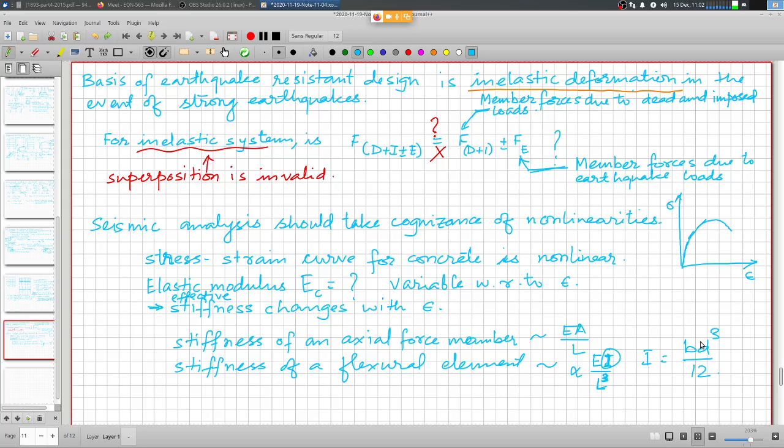And that is why you have so much reservations about the concept of flat slab, wherein the beam is practically merged in with the slab. So the depth is only of the order of 110 or 150 mm, same as that of the slab.